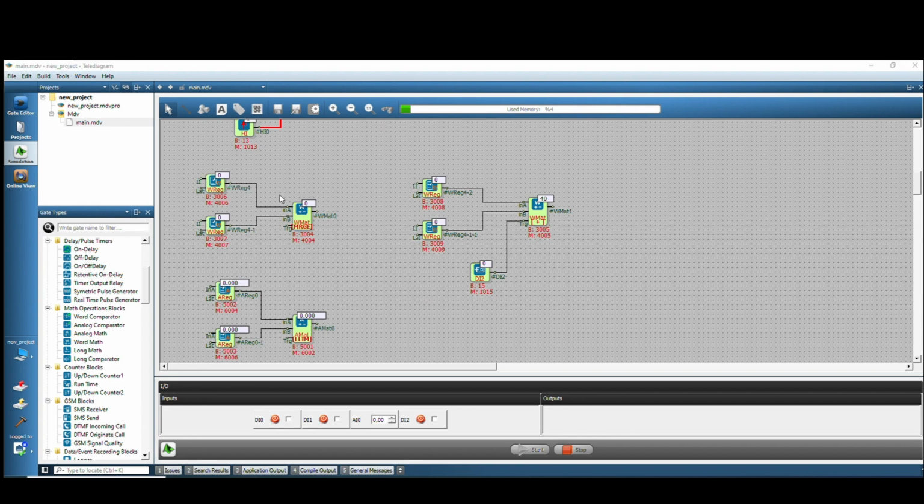As a value, I enter 8. When we also entered 2 to the other, we displayed the value as 520. The reason is this: the input in B represents the 8th to 15th bits. The input in A represents the 0th to 7th bits. Thus, the value of 512 comes from 2 to the power of 9, and we got the value of 8 from 2 to the power of 3, so we transferred the value of 520 to the output.